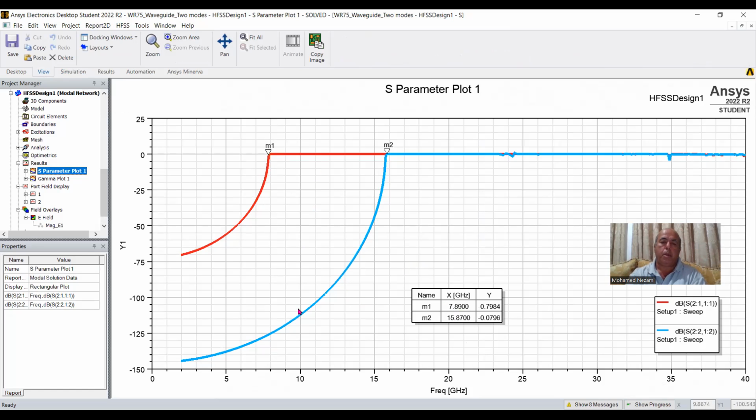So now, if you want to build anything at low frequencies in here, say from 8 gigahertz to 15 gigahertz, you want to make sure that is with a safety margin. That's where you would want to place the usable bandwidth of the lowest order mode. Otherwise, you have to excite the waveguide with the TE20, and that's pretty complex and unusual to do. But you just want to make sure that you stay away from it, or you redesign the waveguide components so that the TE20 mode is pushed further up in frequency.